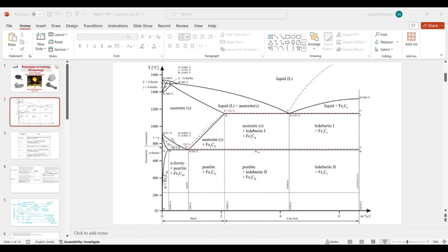So what you have to do during the quenching process is get the temperature down from 750 degrees Celsius to around 200 degrees Celsius within 1 second, or 1.5 or 2 seconds only. Okay, you have just that much time. So you are going to leave this nose. You are not going to get transformation to the pearlite structure. You are directly going to transform your stable austenite structure into martensite. And this phase has very high hardness values, as we have already discussed, compared to pearlite.